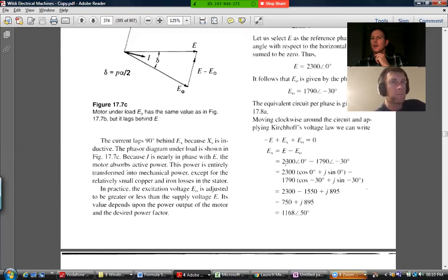So that would be your line voltage, or your grid voltage, if you like, at 0. That would be the E naught that's being induced by the sweeping rotor. They're telling us that it's happening with a 30-degree electrical lag. So the line is ahead of the rotor, it's dragging it around, it's a motor.